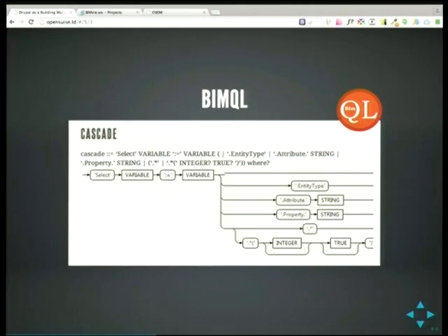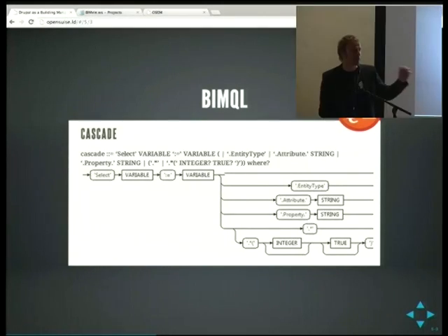Furthermore, just like SQL, there is a BIMQL that you can use to query the buildings. For example, give me all the windows on the 3rd floor that face east, since the ones north usually don't deteriorate as hard as the ones in east and in west, and south, of course.